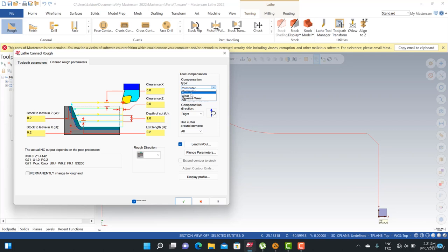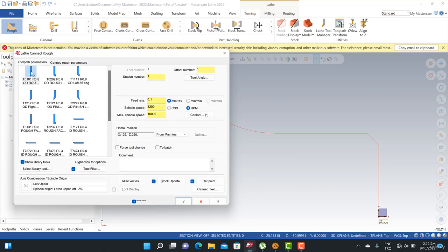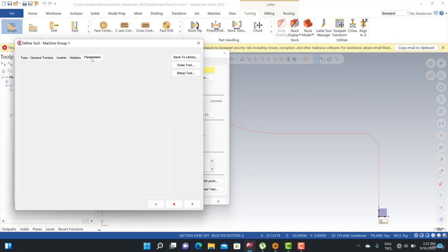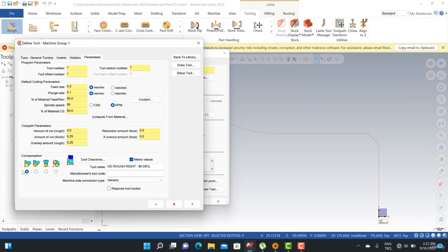So it means that we're gonna get the toolpath compensation code in our G code, and then we can easily handle that stuff on my CNC. So I'm gonna prefer to use the computer. According to my tool radius, it's calculated automatically. So if you would like to change your radius, you need to click here. According to my process, of course, this is also my compensation type.